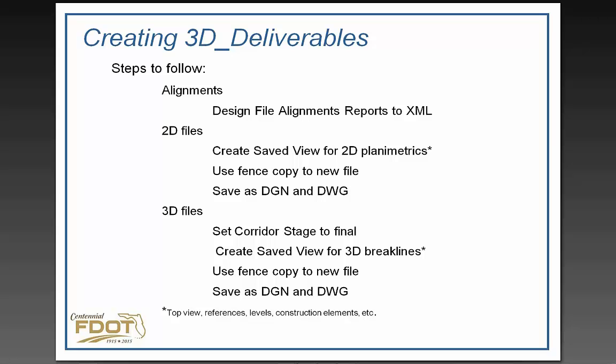We want to make sure we've got the final design stage, which is going to be the tightest interval on our corridors first. And that will also create, like last week we created that intersection, that will also create a better intersection model off of the tighter corridor models. If you remember, we were using the corridor break lines, if you will, the corridor surfaces to create the terrain surface.